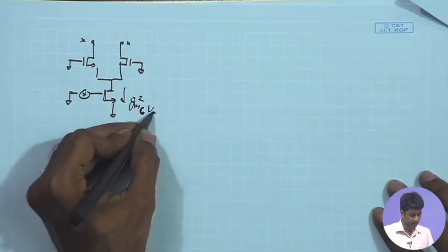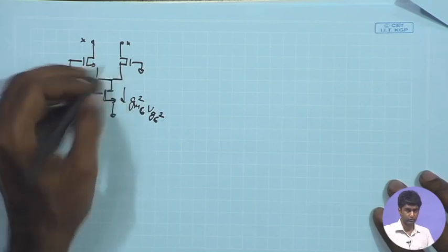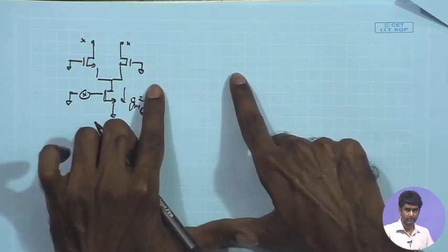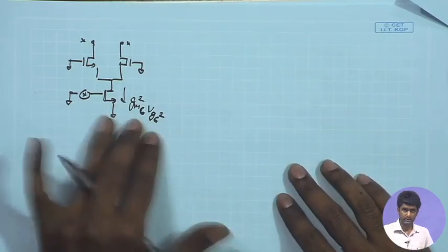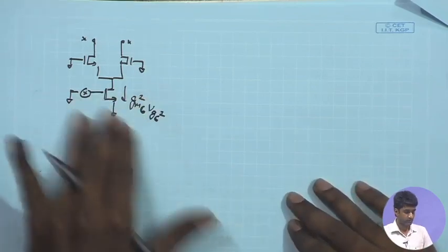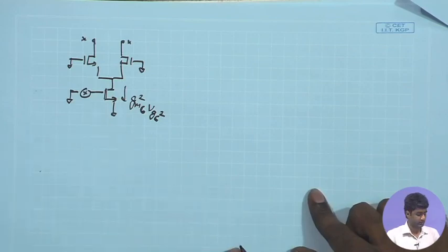That is going equivalently divided into the two branches and getting folded down. Therefore, these two sources are correlated, and when you take the differential output, it is getting cancelled. So its effect is not appearing significantly in the differential output. So we ignore the contribution because of this gate noise as well as the channel current noise.